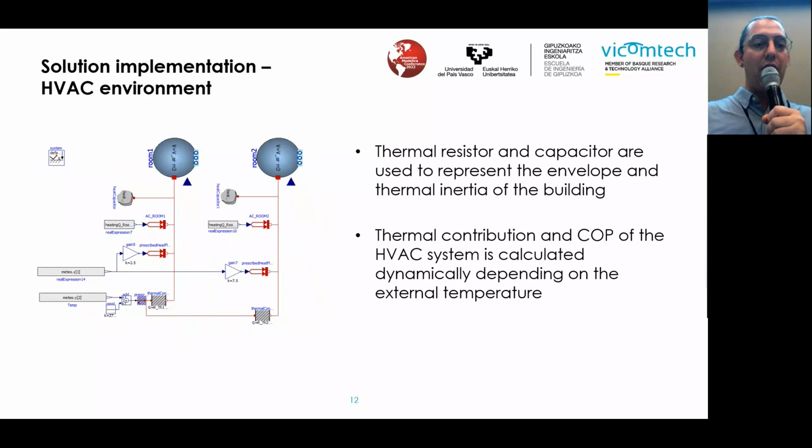All right, so now here you have a simple model that aims to emulate the thermal demands, the thermal loads of the system. The idea here is to calculate the losses to the exterior as well as consider the thermal inertia and the envelope of the building, because you have heat due to irradiation from the sun.